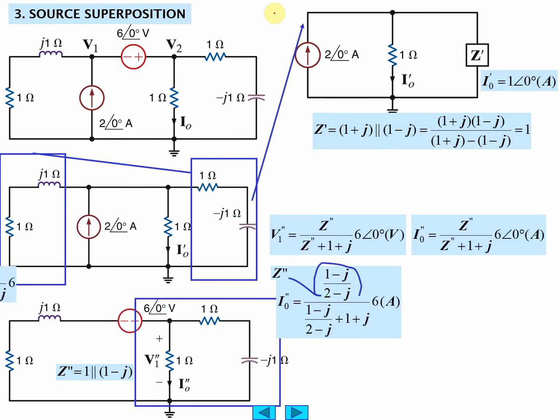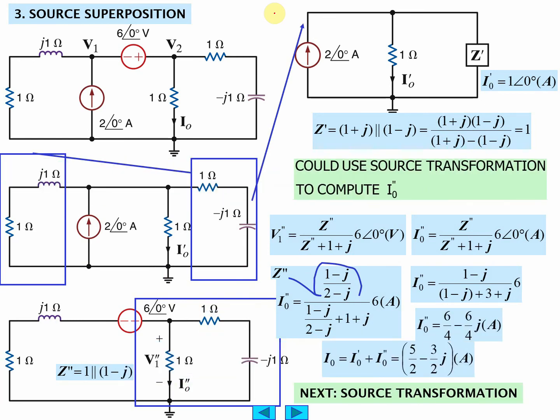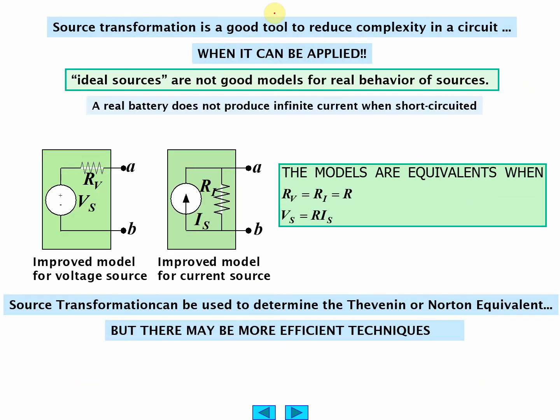I gave you the basic outline of how to go about this problem. And we've done DC problems like this before. And here's Thevenin's again. We're coming back to Thevenin's equivalence. You replace the resistances with impedances of source impedance. And of course this becomes an AC current source, and this becomes an alternating current voltage source. And this guy got flipped around. Take a look at this.